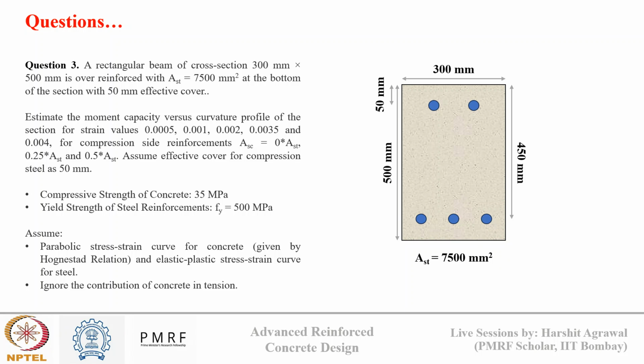Okay, so this again we will solve with the Excel sheet calculator. We'll modify the Excel sheet again this time. So just think what all modifications will be needed now. Just tell me. Okay, so last time you saw we just added one more element, the axial compression, and we added it to the tension force to calculate the total tension capacity. Now in this question, when we are doing a design for a doubly reinforced section, what all changes do we need to make? Can anyone tell me?